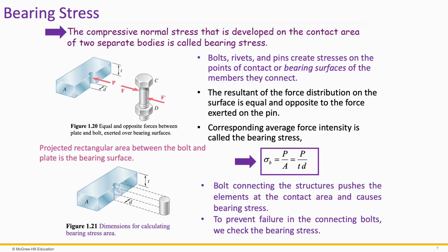Now let's shift our attention to another important type of stress that occurs at connections, bearing stress. Bearing stress is a compressive normal stress that develops on the contact area between two separate components, typically where a bolt, rivet, or pin presses against the surface of the plate it passes through.